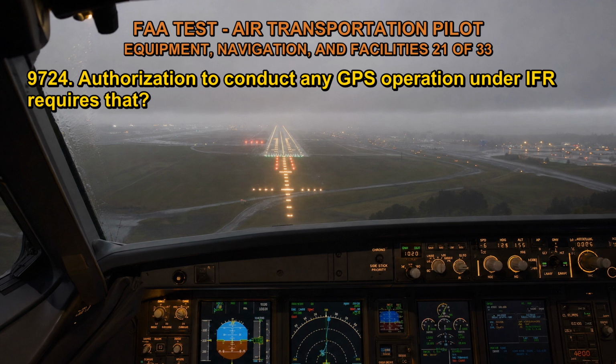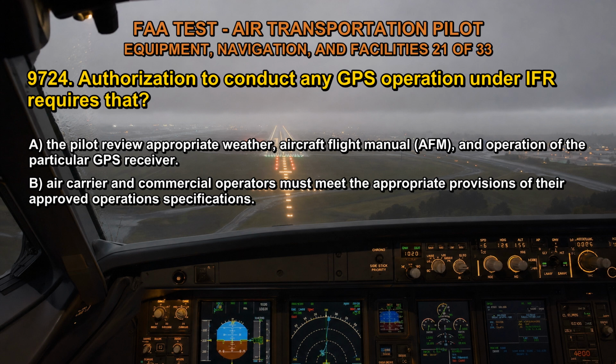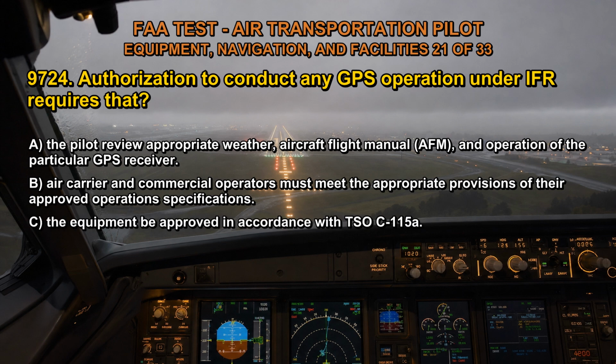9724. Authorization to conduct any GPS operation under IFR requires that A. The pilot review appropriate weather, aircraft flight manual, AFM, and operation of the particular GPS receiver. B. Air carrier and commercial operators must meet the appropriate provisions of their approved operation specifications. C. The equipment be approved in accordance with TSO C115A.